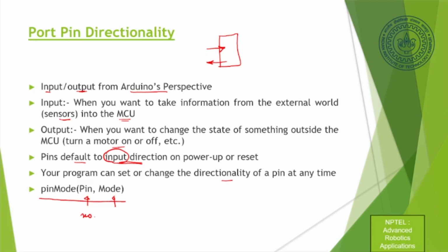Before we run the program, we have to set the pins to input or output. If you're taking a sensor input, it becomes an input pin. If you're driving a motor, it becomes an output pin.